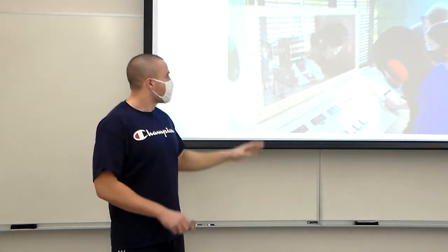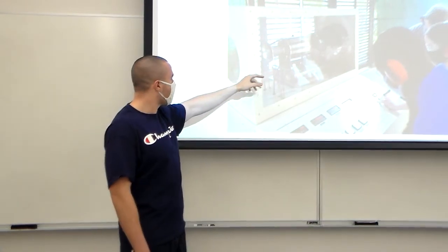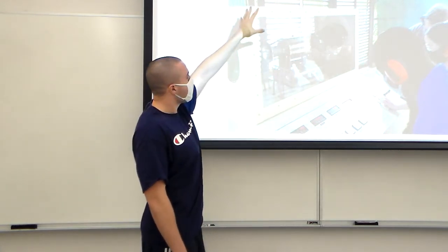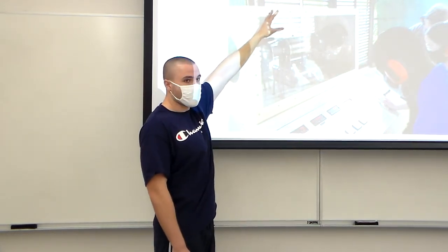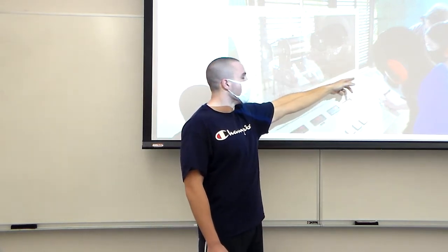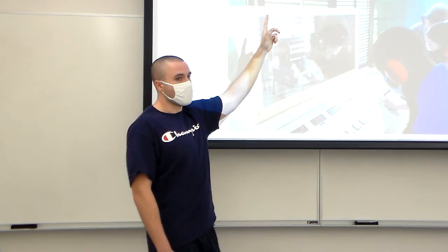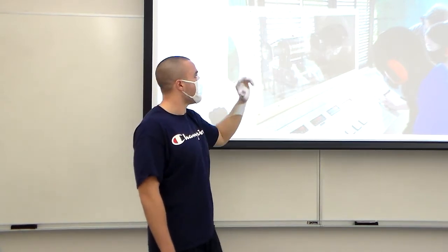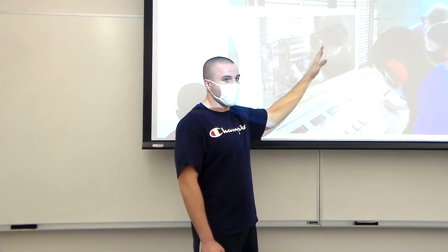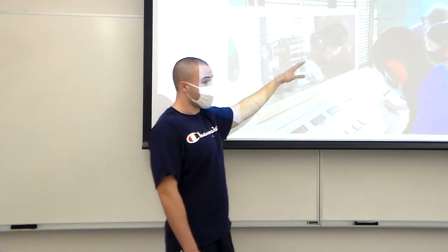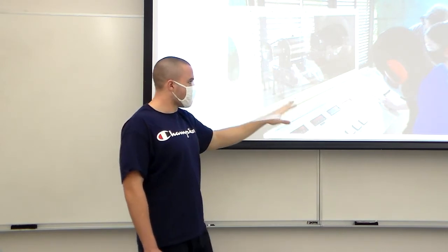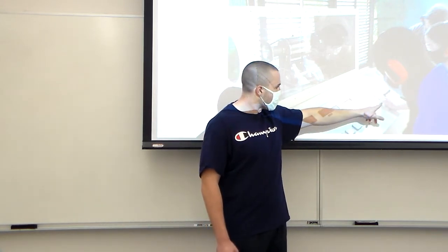So, some operating conditions. This is the apparatus itself. This is the inlet. Over here is the outlet, and you can't see, well, you probably see a little bit, there's a canopy above us, a little tent. And so what you want to do is make the outlet flush with the canopy end, because this is going to exhaust really, really hot air as well as just fuel, and you don't want to be anywhere near it. And when you're running this thing, what you want to do is, like Miranda's doing here, you want to take the throttle.